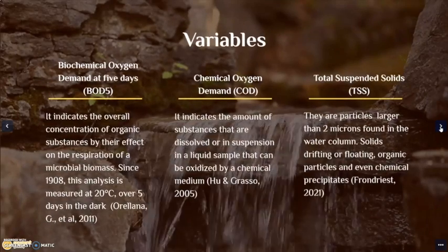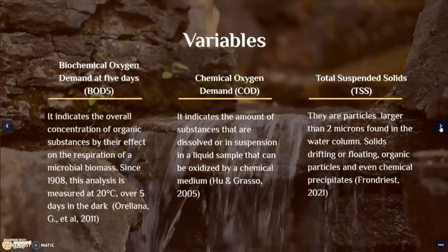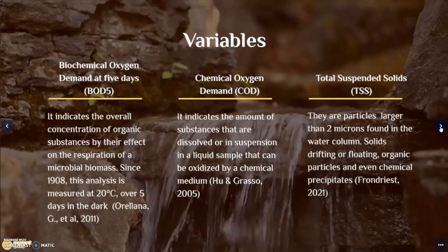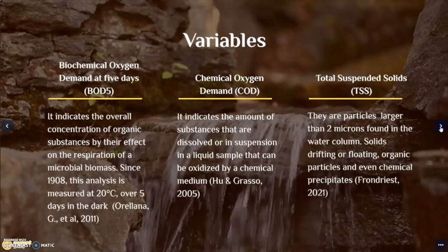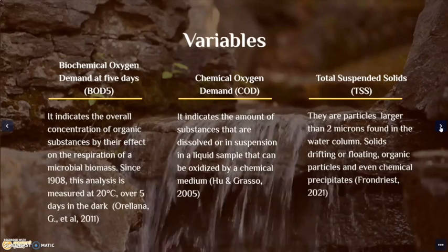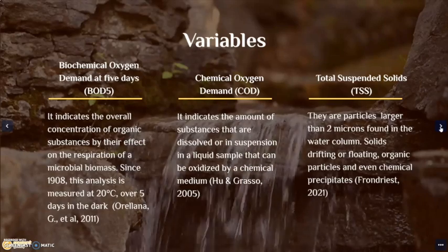The 8 variables monitored are biochemical oxygen demand at 5 days, which indicates the overall concentration of organic substances by their effect on the respiration of a microbial biomass. Since 1908, this analysis is measured at 20 degrees Celsius over 5 days in the dark.